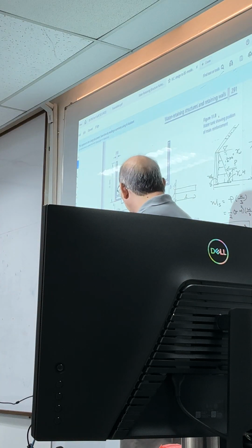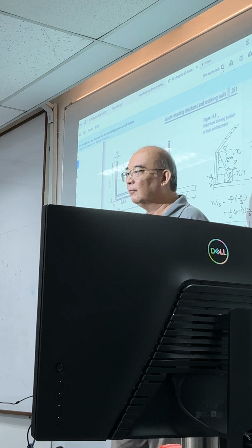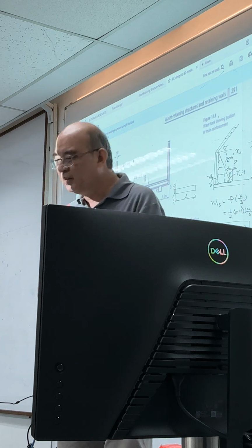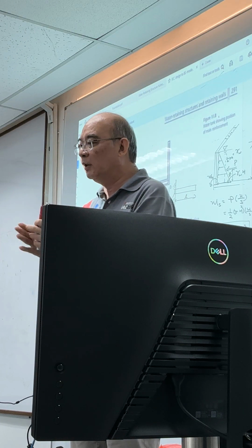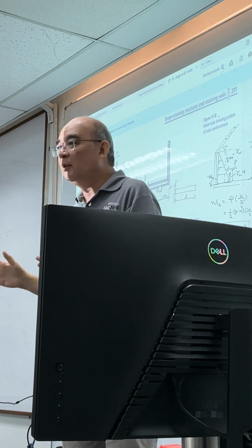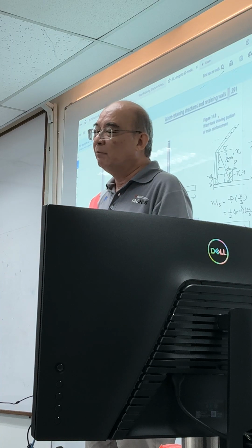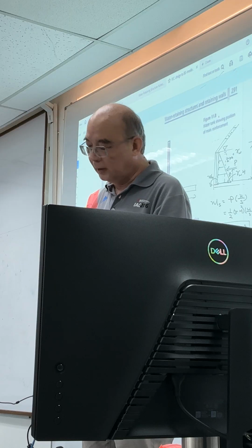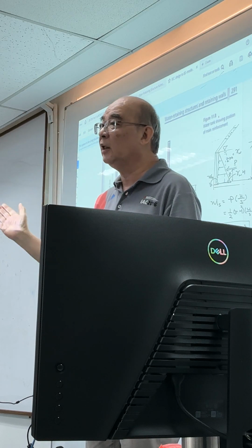So basically it extends 1.5 D inside. Okay, and this is in the British code. British code says, when you look at the cantilever, the effective span of the cantilever is this. But most of the people, I just basically ignore it. I just take the clear span.